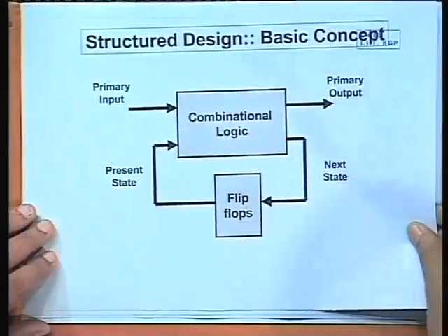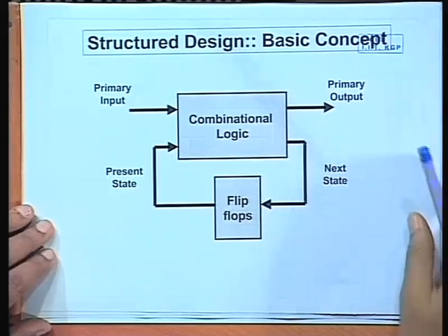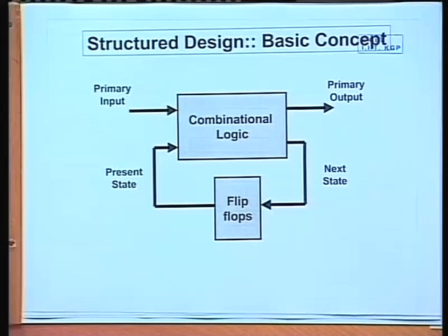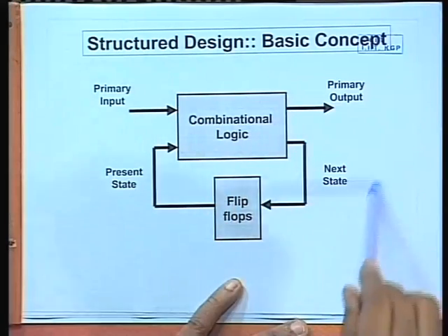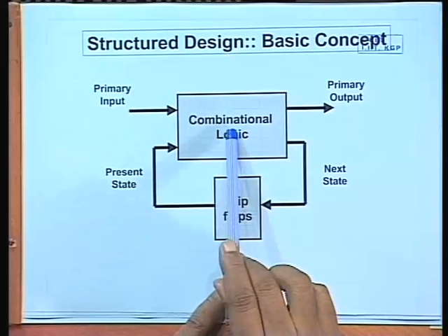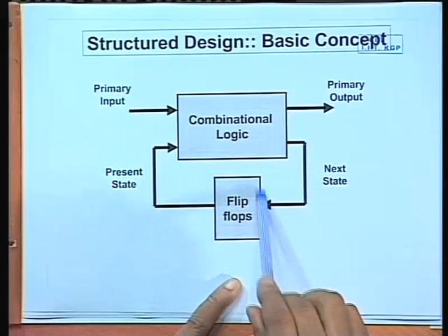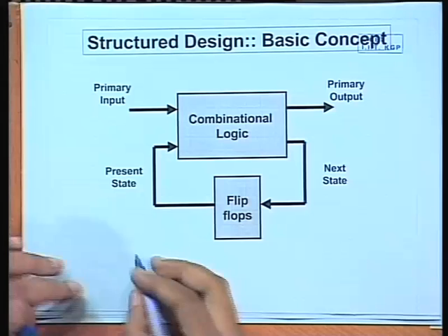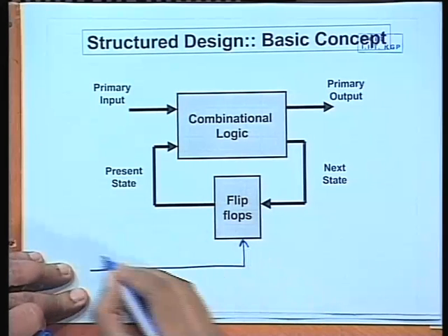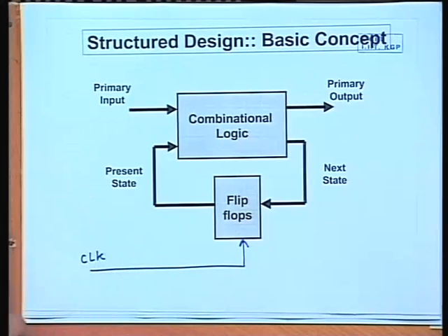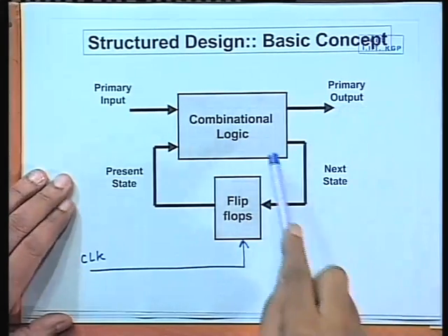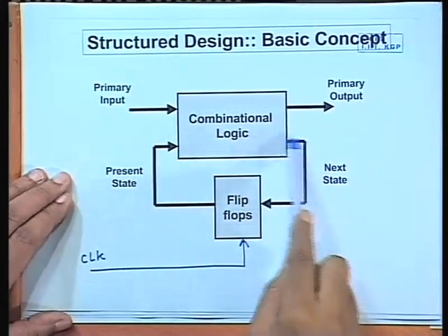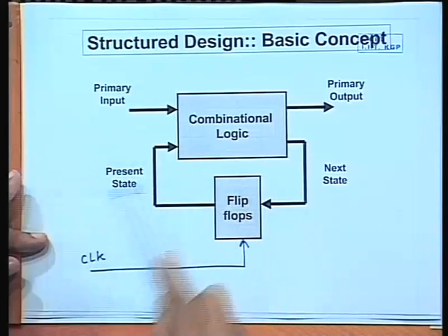Structured design tries to attack the problem from a different viewpoint. The structured design for testability techniques are primarily aimed at testing sequential circuits, and as you know, a sequential circuit can be modeled like this, where the combinational portion and the memory portion, the flip flop portion, can be separated out. Of course, I have not shown the clock, which will be feeding the flip flops. There are primary inputs, primary outputs, and the state variables: this is the present state and this is the next state. So, when the clock comes, the next state becomes the present state.